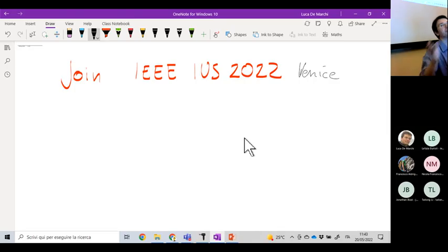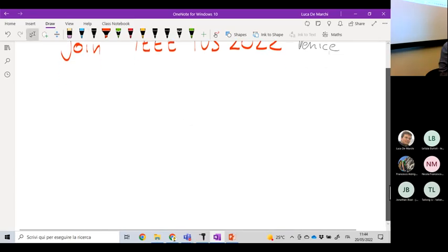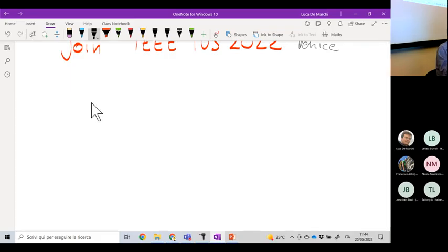Okay, let's jump back to non-idealities of op-amps. So we have started the discussion of several non-idealities, in particular related to the limited gain of the op-amp. Then we have discussed the effect of the offset. And in the previous class, we have also introduced the problem of having non-infinite input impedance in the input terminals of the op-amp, and therefore currents flowing into the op-amp.